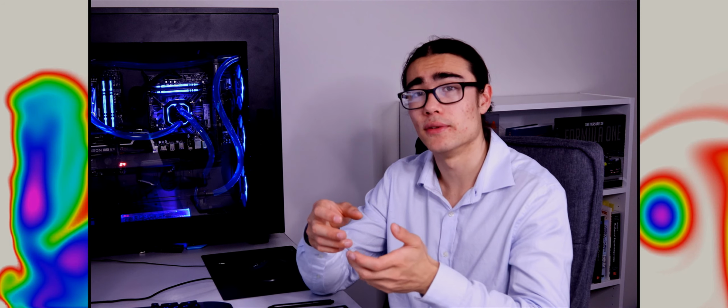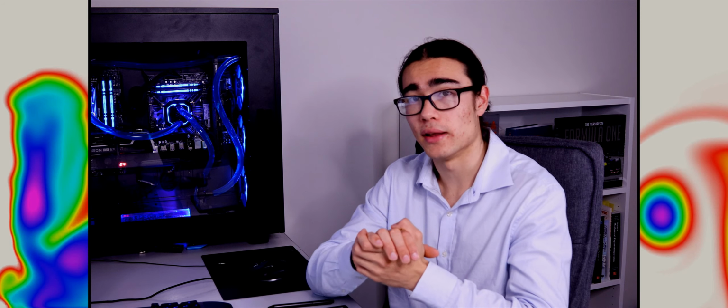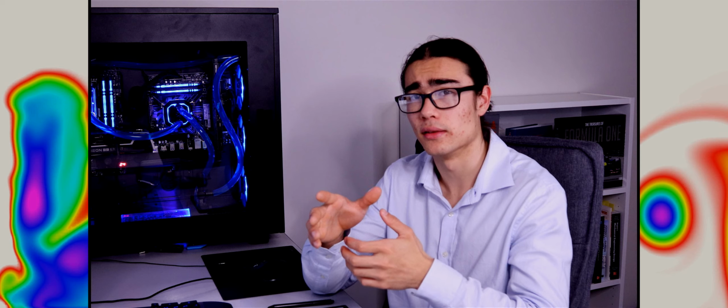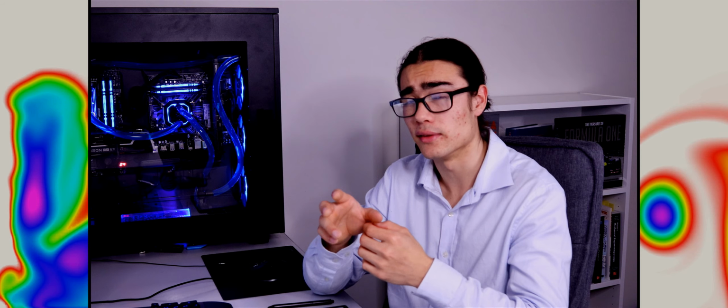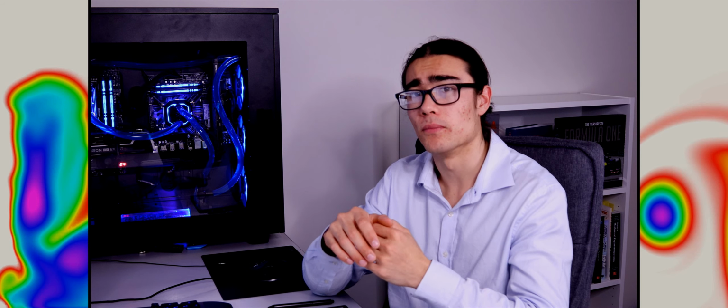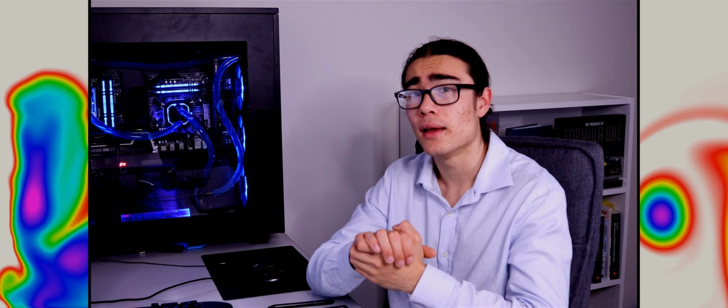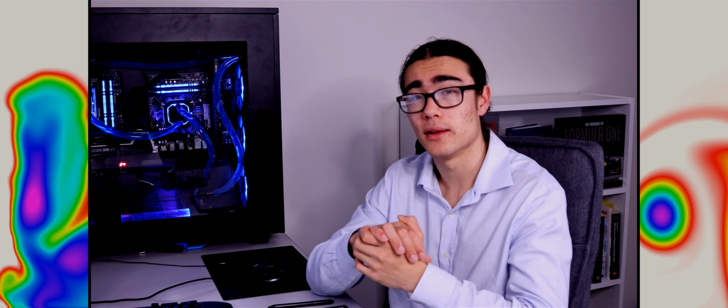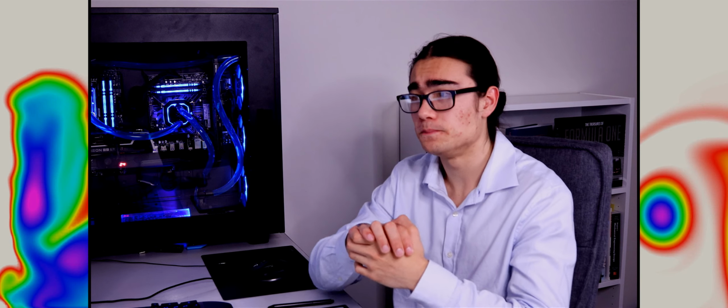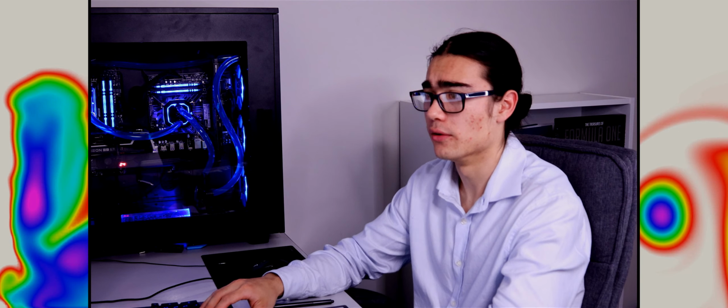So I ran some CFD. These are just simple cases. I perform statistical analysis on the user points and use the steady state approach. Ideally you'd use a transient. I just don't have all the computing power in the world. 3.5 million cells, y plus less than 1. Now, here's what I found.